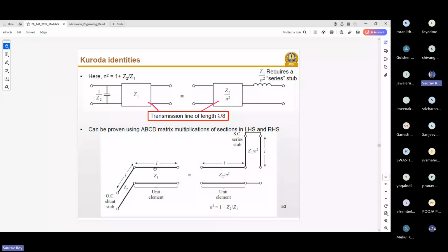Another thing you should notice is that all of the line sections are of length L already. So the length does not change. Only the characteristic impedance of the microstrip line section changes. So if that changes, how will it affect our design? As you know, if we know the characteristic impedance, we can calculate through the LineCalc tool or any tool what should be the width of the microstrip line. That is how you can calculate and design a microstrip line.